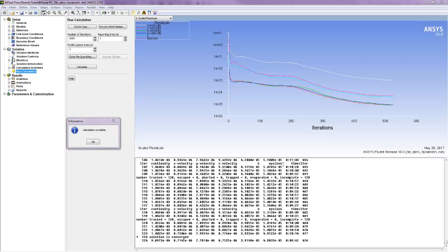Okay, see, we get converged now. It says solution is converged, it means this value has reached the acceptable value. This is done in 524 iterations. Maybe you can improve your iteration count, reducing it by changing your mesh. Maybe you can improve by changing your mesh type into hexahedron or hex dominant, or you can do other things like map face. Maybe it will be better.